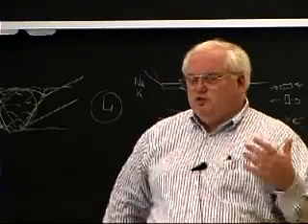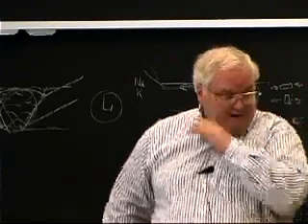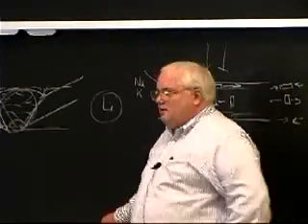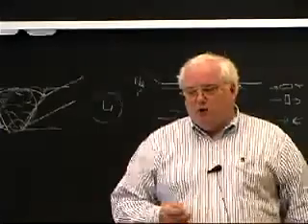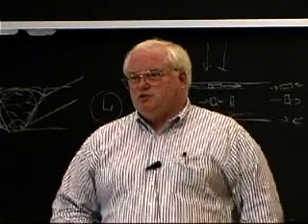And for all those of you who are surface ship guys, how thick's the hull? About a centimeter thick, right? So it's a big problem. Whereas submarines, which are thicker, and I can't tell you, because we don't know, right? What the thickness of a submarine hull is, but it's considerably thicker, you end up with very heavy residual stresses from the welding operation.